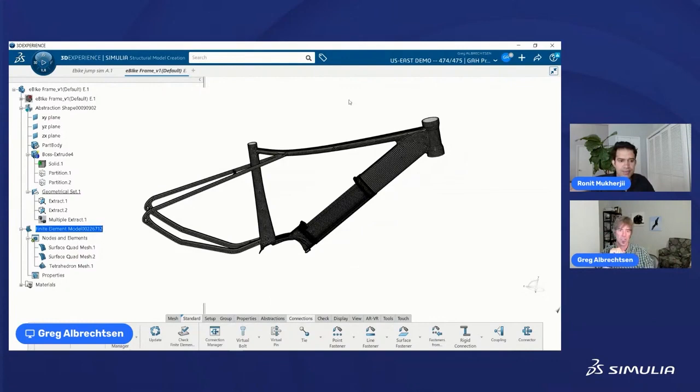K is basically what we call the stiffness matrix of this. It's just a big, huge mathematical matrix representing how this whole structure behaves. And as we know from structural mechanics, we can relate F to stress and strain through Hooke's law and some other things like that. So that's it. Sorry, that's the hidden black box secret of FEA. It's just one big spring equation. If only all the setup was that easy, right? That's your 600 level graduate course right there, summed up. F equals kx.